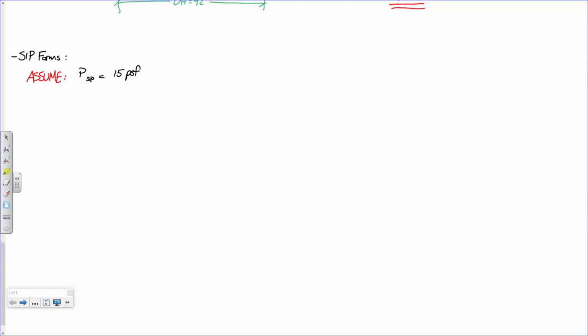But I do want to add another issue. You're bringing up an interesting point within the world of bridge engineering. In order to shave weight off the bridge, a lot of folks will order SIP formwork that comes with the flutes, where you get that little bit of extra concrete, filled with basically foam, like the big foam sheets. The philosophy is that by filling it with foam, it's not being filled with concrete. So that is an option, and then you can neglect it. If you want to account for the weight of the foam, go ahead, but that really is going to be negligible. I'm actually not the biggest fan of it. I kind of think you need to fill the entirety of the form. That's just me.